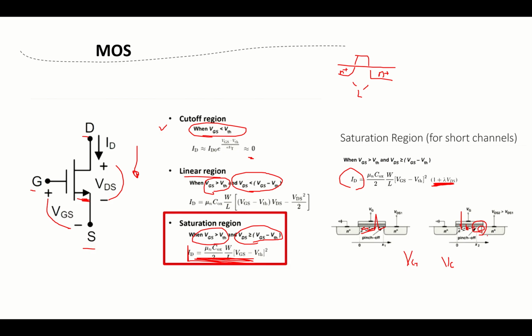Here, VG minus VC will be really small because we have a drain over here with high voltage. It will be almost at VT, where it can't maintain the saturation region anymore. But because of the large electric field over here, it can still pull the electrons from the channel directly back to the drain, giving the current. And that's part 1 of this introduction.